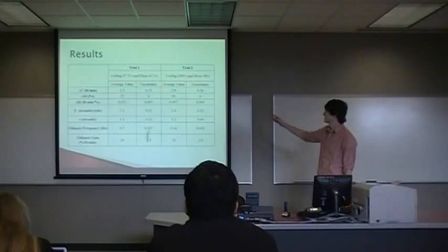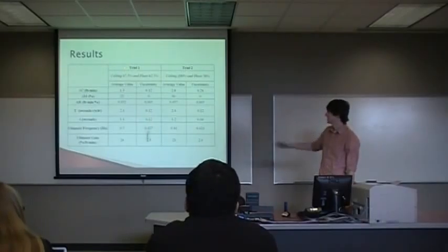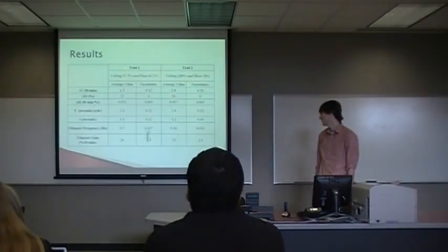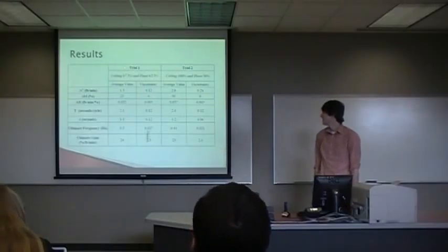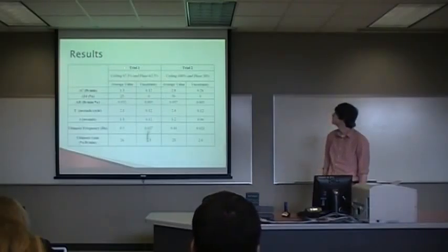Trial 1 represents the first plot, and trial 2 was the other one, the higher ceiling. Delta C and delta M varied between the two because the ceiling and floor were different, but in proportion they were still the same because the amplitude ratio remained pretty much constant. The ultimate frequency and ultimate gain also were within reason in both trials.